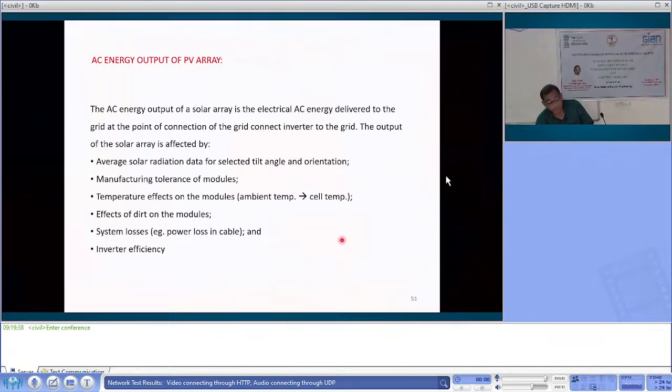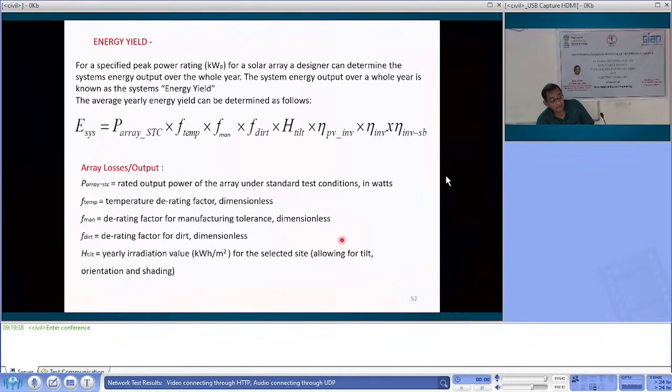Then what are the factors that are mentioned here? This is the formula that gives energy yield, where rated power output is the first factor at standard test conditions. Practically cell temperature 25 नहीं रहता है. Okay, in winter it will be low temperature outside. Ambient temperature will change your cell temperature. In your simulation we consider that the insolation is fixed, okay, and temperature is varying, or temperature, cell temperature is 25, insolation varying. Practically दोनों vary होता है.